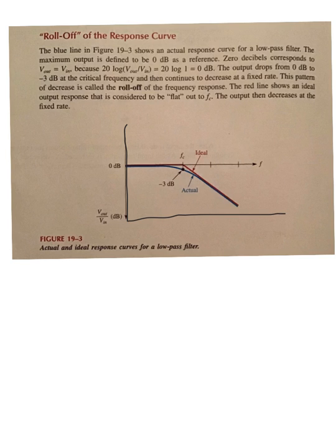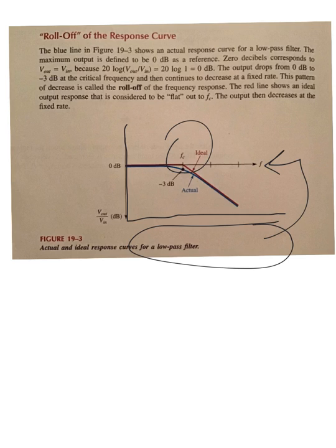They've just taken the axes down here and moved it to the top, and it shows the circuit losing voltage when it goes past the critical frequency, or the minus 3 dB point, or the 0.707 point, or the 70% point. This term roll-off, the pattern that you're seeing, the decrease, is called roll-off. And the roll-off is consistent.